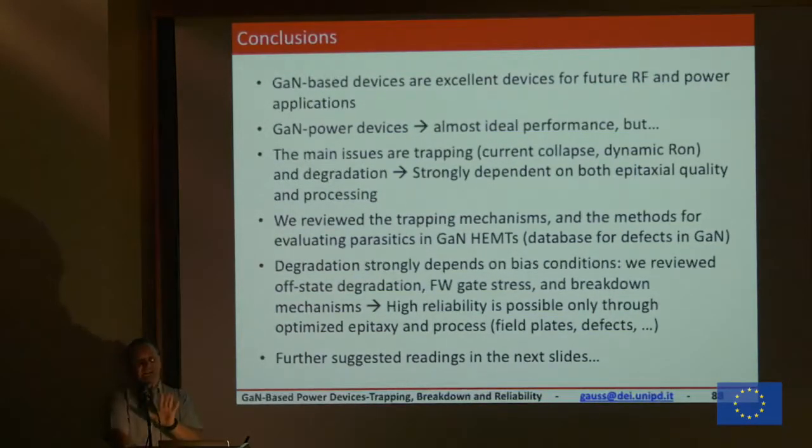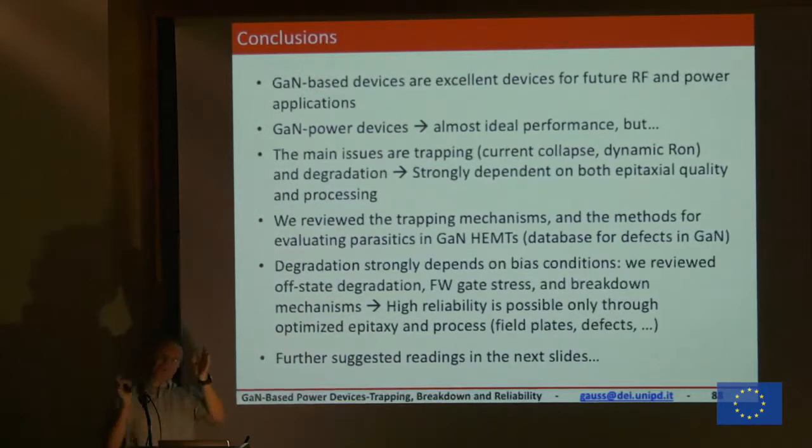The reliability is still not completely understood. And we don't know very well which are the procedures to establish the reliability of gallium nitride devices. In other words, in silicon, we know everything about the physics, and we know the acceleration law. So I know that if I stress my device at higher voltages and at a higher temperature, I'm able to extrapolate, as we have done before, my lifetime at a lower temperature, lower voltage. In GaN, we are not sure that we know how to qualify our product.